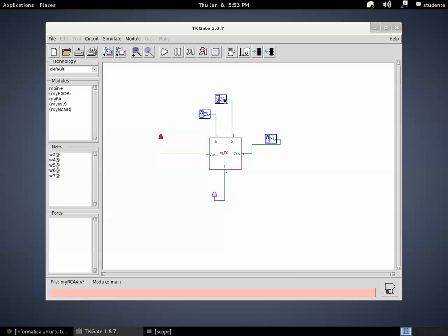Now, if we have just one of the two input bits at 1 together with the carry in, then the result is 0 and the carry out is 1, and in the other case as well, while in case of having a carry in with both A and B taking value 0, then the sum is 1 and the carry out is 0. So our full adder works properly. This means that we are ready to use it, to compose 4 of them in order to realize our 4-bit ripple carry adder.